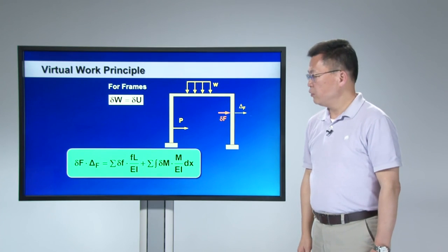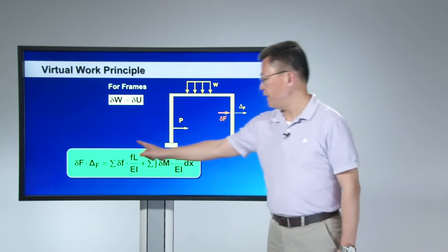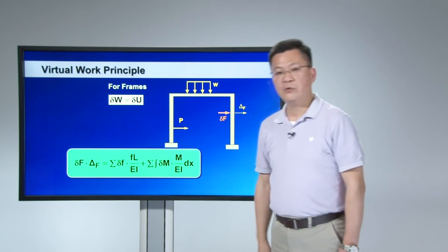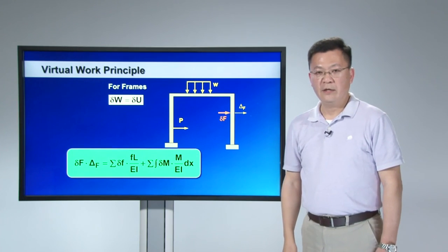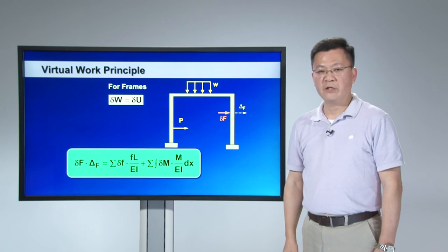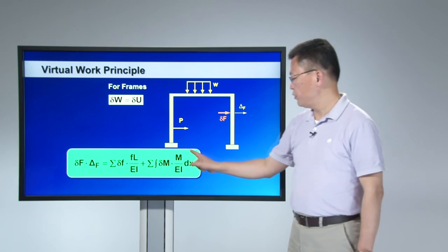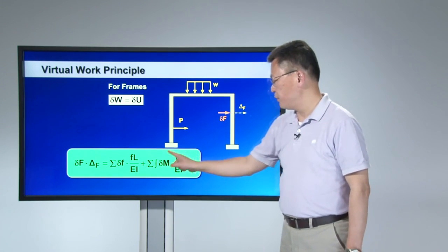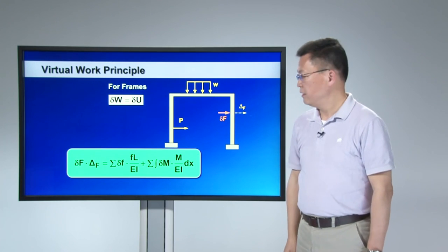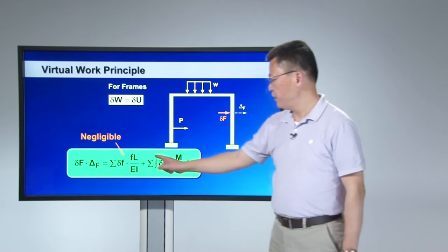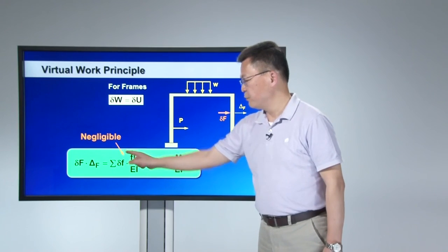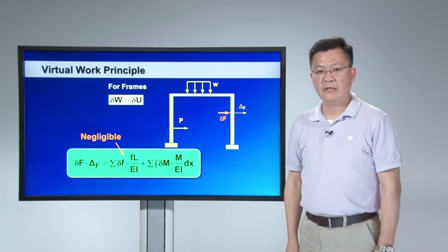Quite normally, the contribution of axial force to the strain energy is very, very small compared to the strain energy contributed by the bending moment. So in practice, we usually ignore the contribution of the axial force in the calculations.